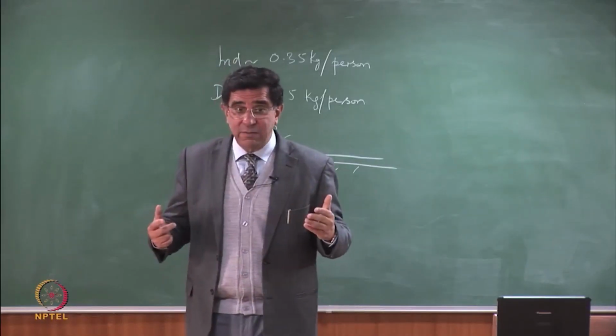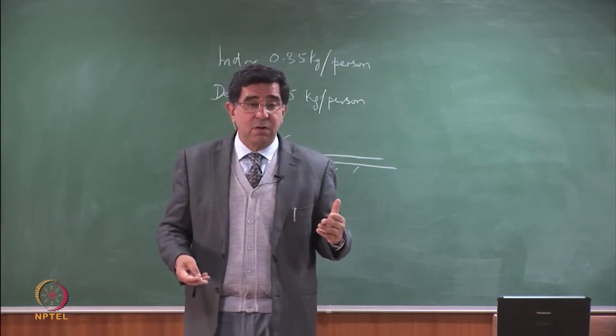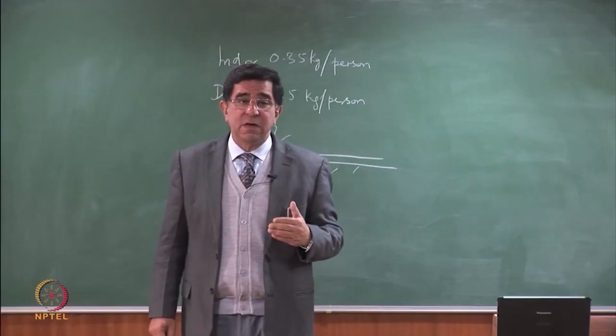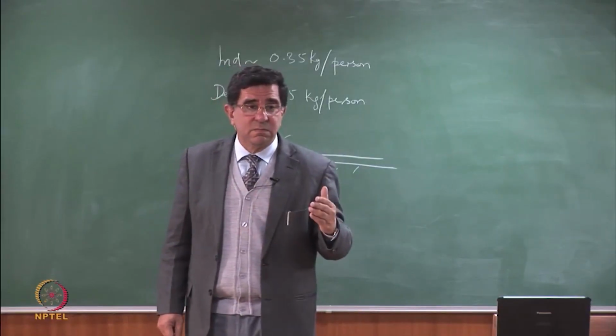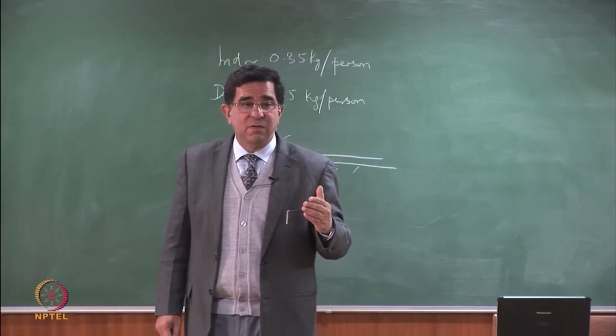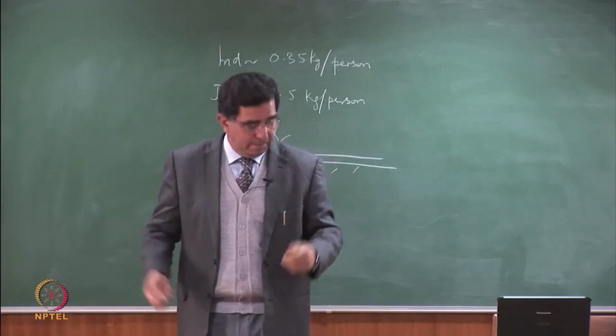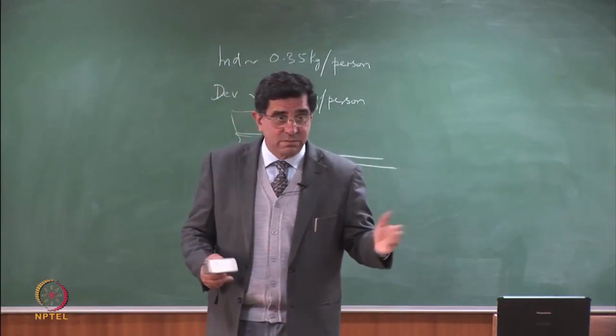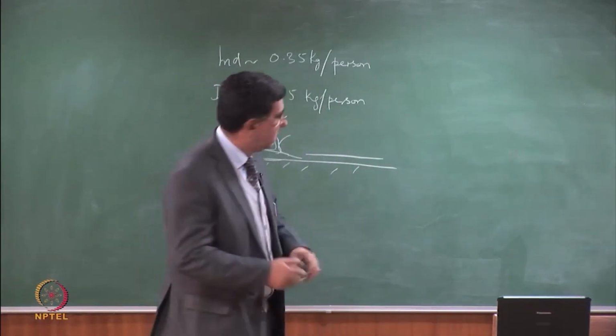To be able to cover the landfill, are we talking of an intermediate cover or are we talking of a final cover? Please understand that the intermediate cover is slightly thicker than a daily cover. It's not an impervious cover. A daily cover gets covered by another cover within a few days, another cell within a few days.